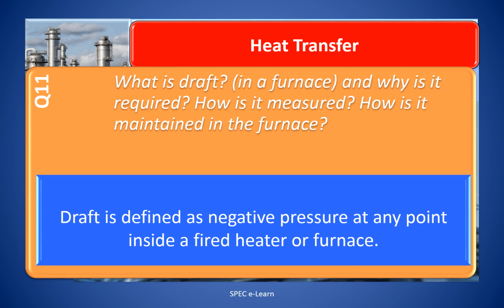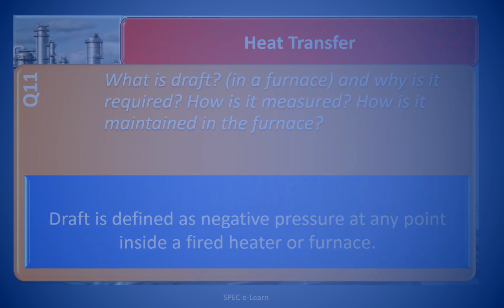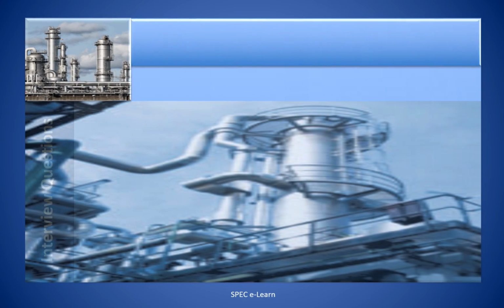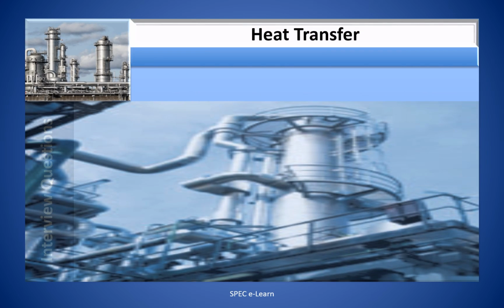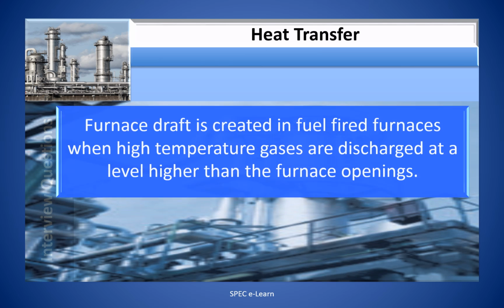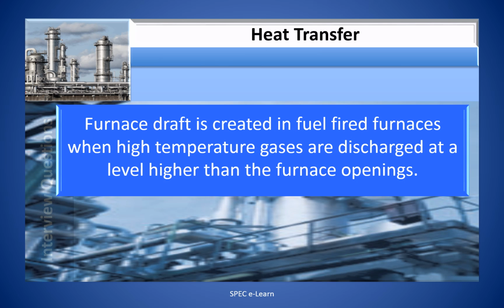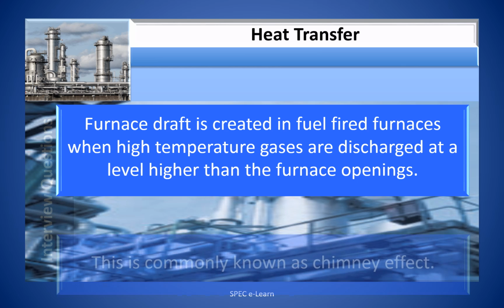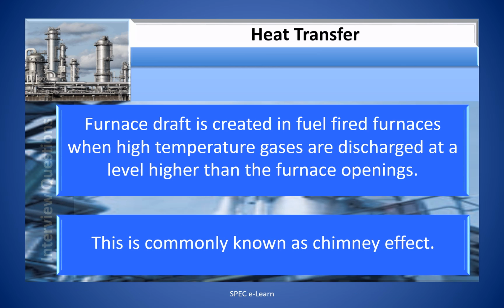Your time is up. The answer. Draft is defined as negative pressure at any point inside a fired heater or a furnace. Furnace draft is created in fuel-fired furnaces when high temperature gases are discharged at a level higher than the furnace openings. This is commonly known as chimney effect.